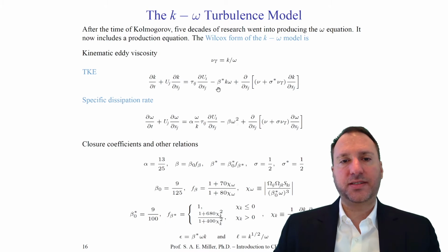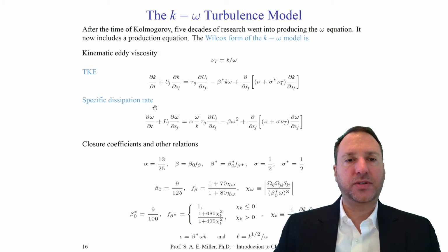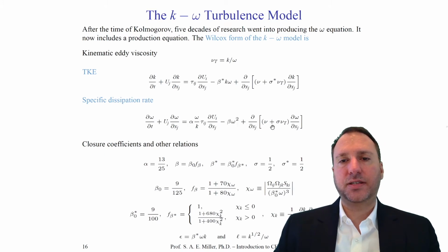It has almost the same exact form. It's a beautiful set of equations. You can go down and compare each term side by side and see the differences, and they're almost being tracked exactly the same. This is rather elegant too, because in the CFD code, you have to calculate many partial derivatives. You can use exactly the same discretization scheme and grid for these types of variables, just replace k with omega for each case. It saves on programming and implementation. I believe that this is by design too.